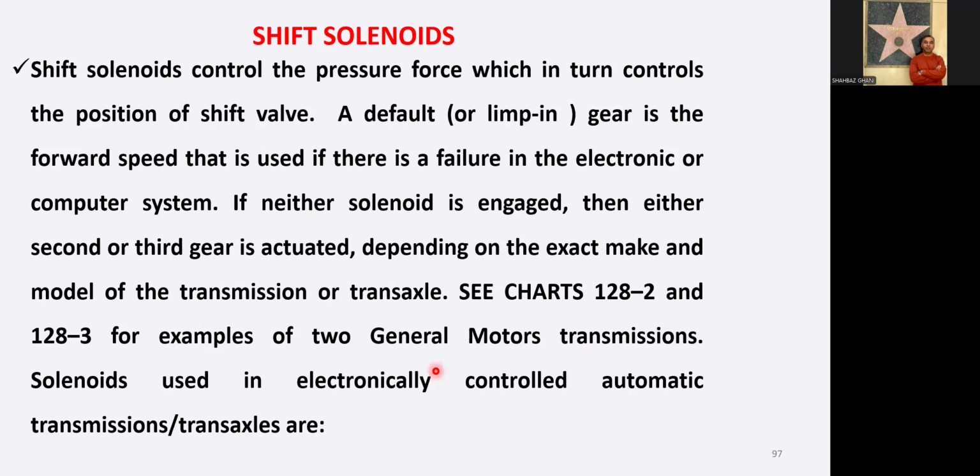Now, shift solenoids, which we are using in this whole electronics, adaptive learning, and input and output sensor system: all the signals go to the solenoids. Those shift solenoids control the pressure force, which in turn controls the position of the shift valve.